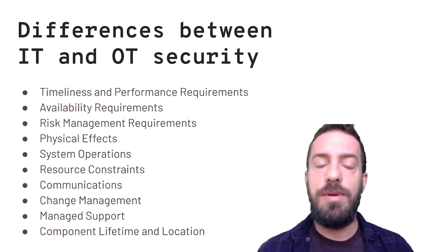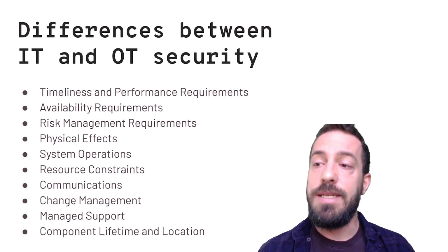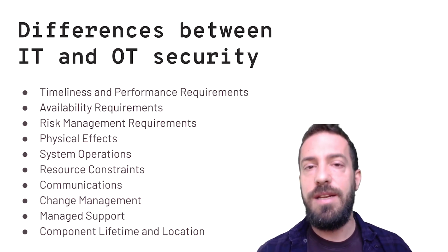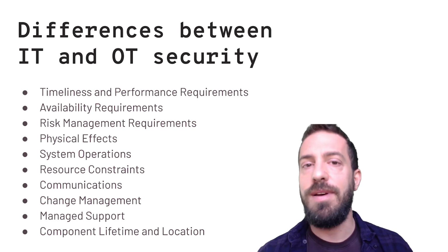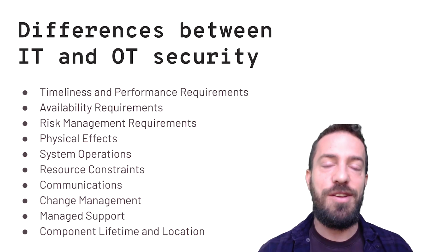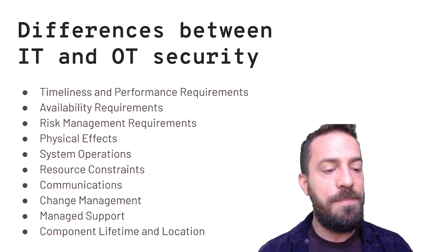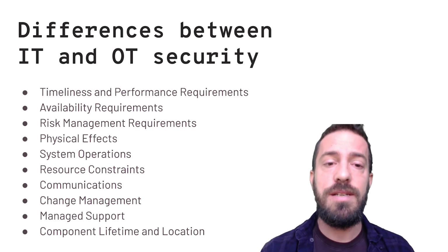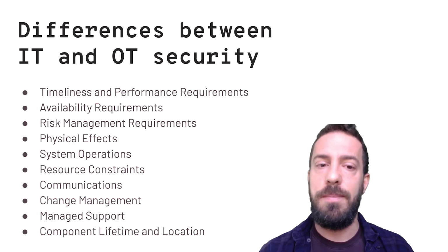Another prominent example we'll see later also is rebooting. You have your machine, your phone, it says a new update is available, you have to restart your computer. Everybody's kind of upset and annoyed, but at some point you do it, right? But this is not the case in OT. If you have a security patch, you cannot just restart the PLC.